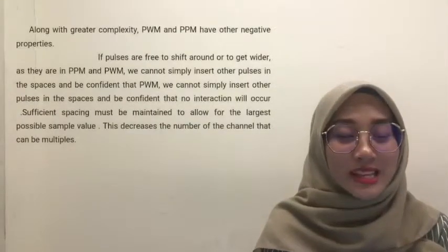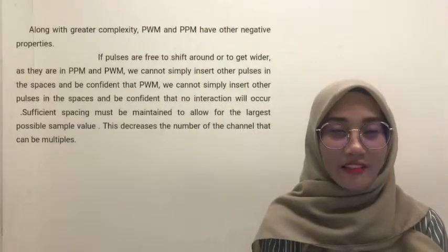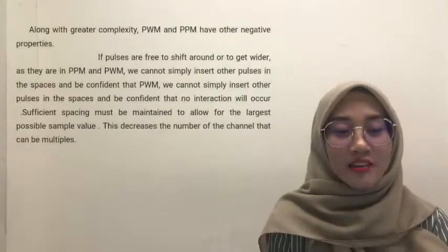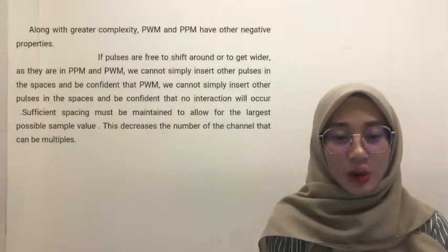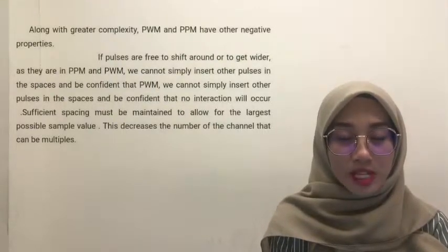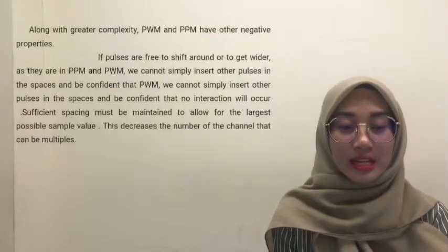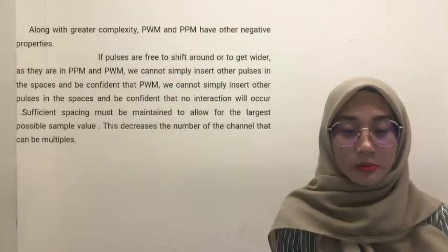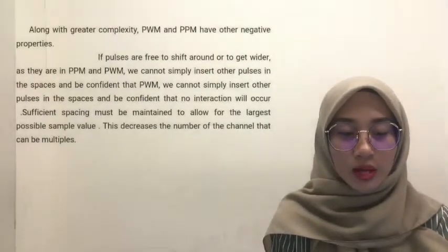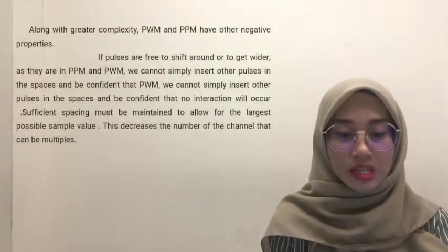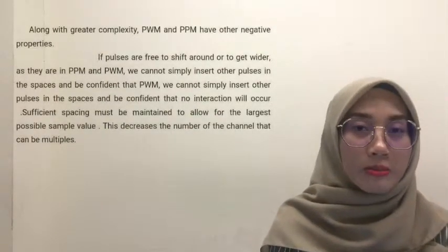Along with greater complexity, PWM and PPM have other negative properties. If pulses are free to shift around or to get wider as they are in PPM and PWM, we cannot simply insert other pulses in the space and be confident that no interaction will occur. Sufficient spacing must be maintained to allow for the largest possible sample value. This decreases the number of channels that can be multiplexed.